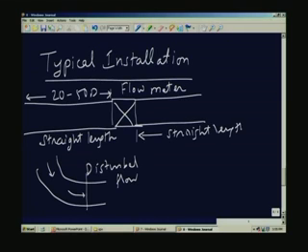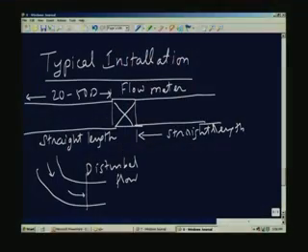downstream of the meter. If we do not want to have any effect of the downstream and the upstream, we need some straight lengths both before and after the flow meter. The flow meter itself is now either one of the 3 we have. It may be an orifice plate, which of course will be smallest in terms of the length. The nozzle will be slightly longer, and the Venturi, of course, will be a very long installation. The length of the Venturi is the longest of the 3.